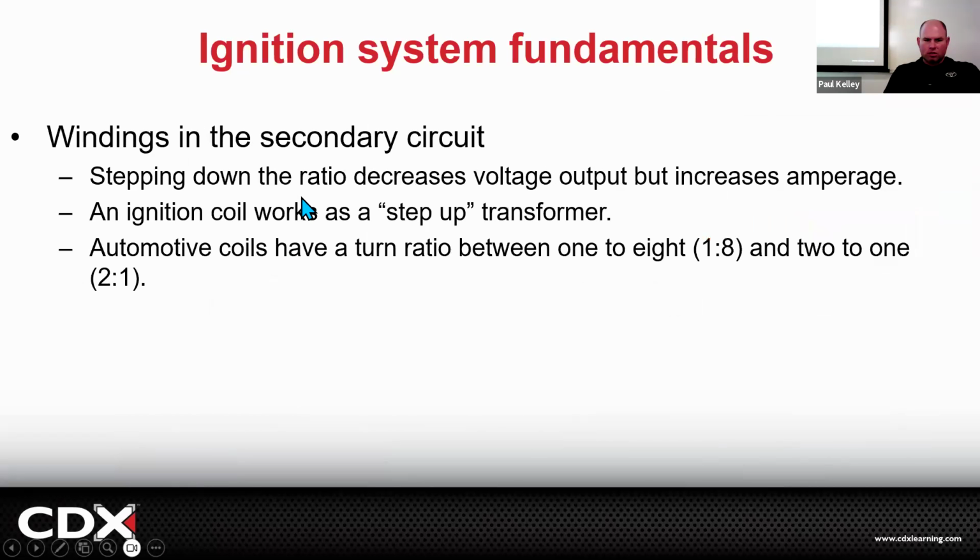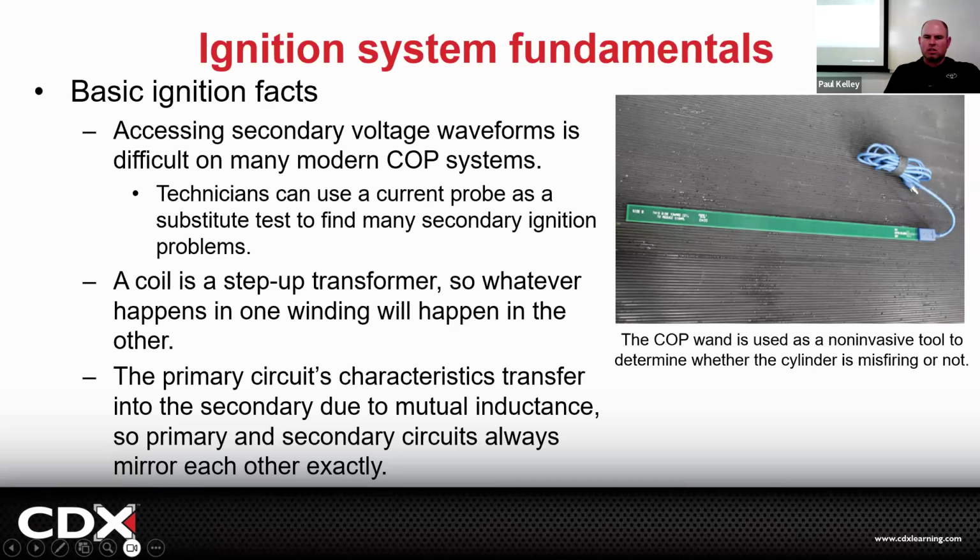So when we do some of this more advanced diagnosis, we may use something like a wand, or some sort of attachment to a PicoScope that's going to measure it through induction, right? You can't physically probe onto it, but you can measure it through induction, the same way the primary induces into the secondary.